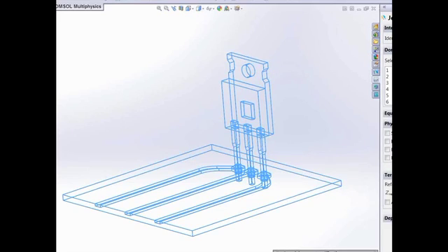And once that is done, you will see that the COMSOL model tree appears on the left side, where you usually have your SolidWorks feature tree, and then to the right you have a window showing the settings. So if I click on a node, I will see the settings on the right side popping up for that particular node of my model.